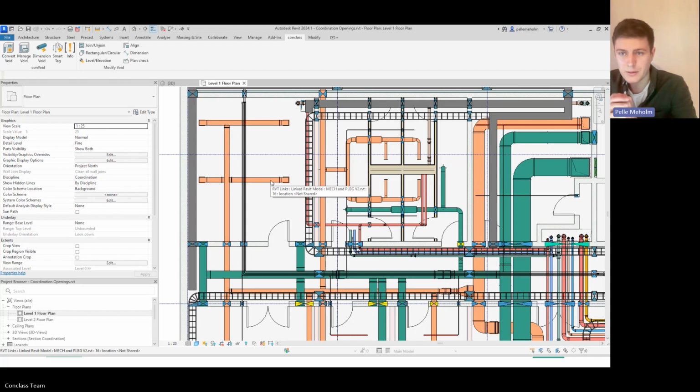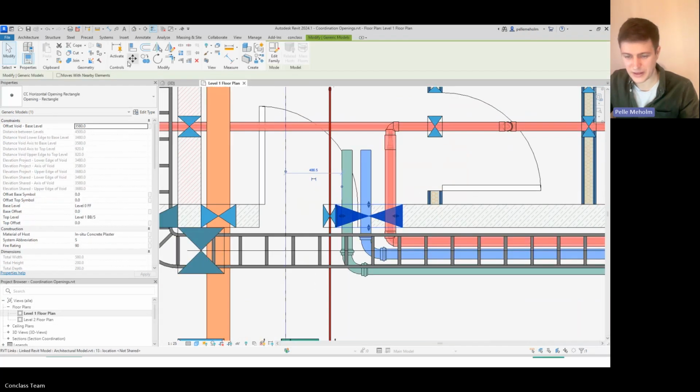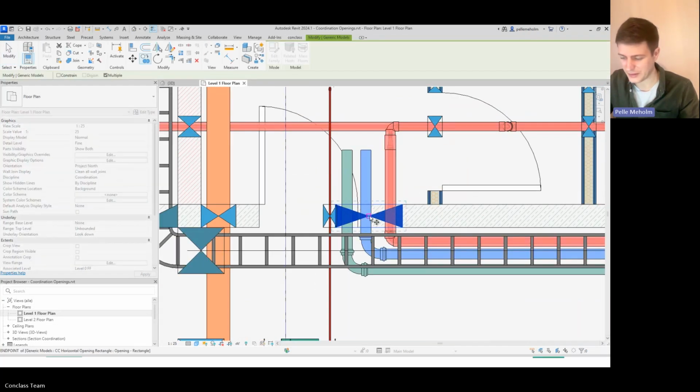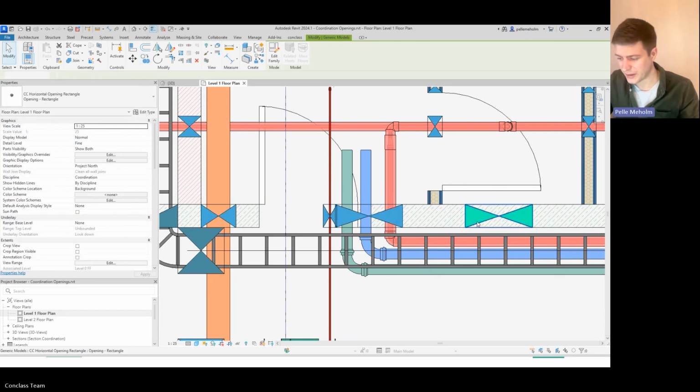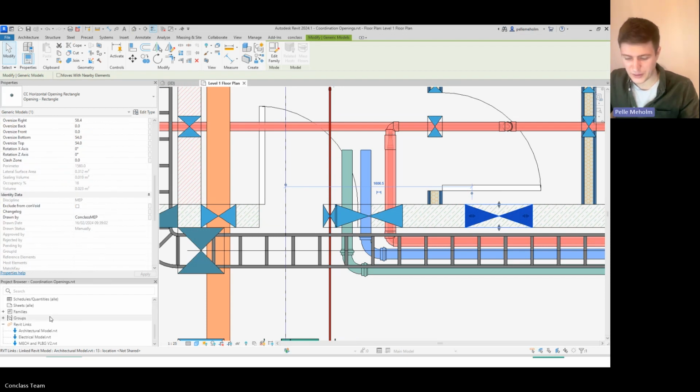Can you edit holes manually after running the program? If you pin a hole, does it stop it from being edited the next time you run the software? Yeah, you can actually just place openings manually at any time. Meaning, if I want to copy one opening, this opening will be marked as manually placed. So it's not connected to the ConVoid process.